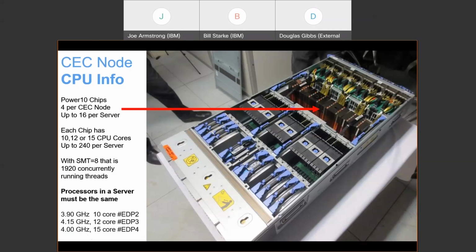Now, note that it shows the clock speed there, but it actually runs in a range. When we came out with Power9, we have the range, and depending on the workload, the clock speed can vary. So if all the cores are really busy, the system is running at 100%, your clock speed will drop, and it mostly drops because the voltage regulators can only give so much voltage to every single socket. And so they max out what the voltage regulators will provide to every chip. But if your system isn't running 100%, then your voltage goes up to these maximums.